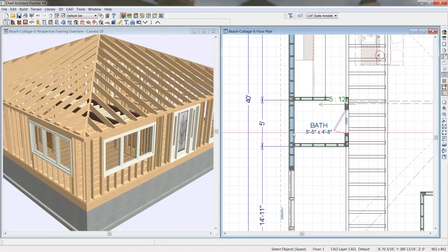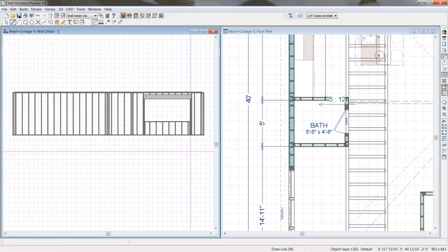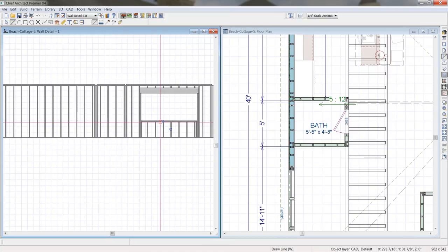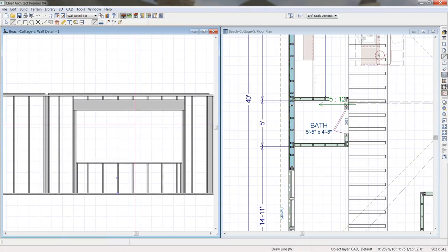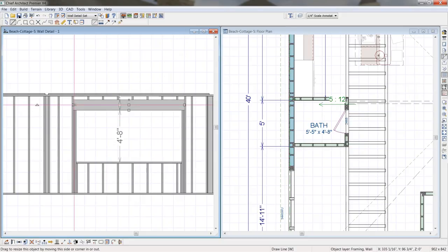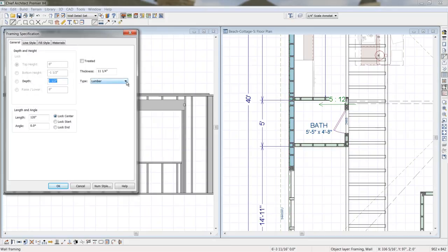And if you select an individual wall, let's go ahead and select this outer left wall, we can actually get an individual framing takeoff. And you can see if I zoom in here, particularly where we have that window opening, you can select any of these objects. You can easily modify it, pull it back, adjust it. If you double click on it, again, you've got that framing dialog. You can choose the information about it. You can change the thickness and all of the dimensions about that.